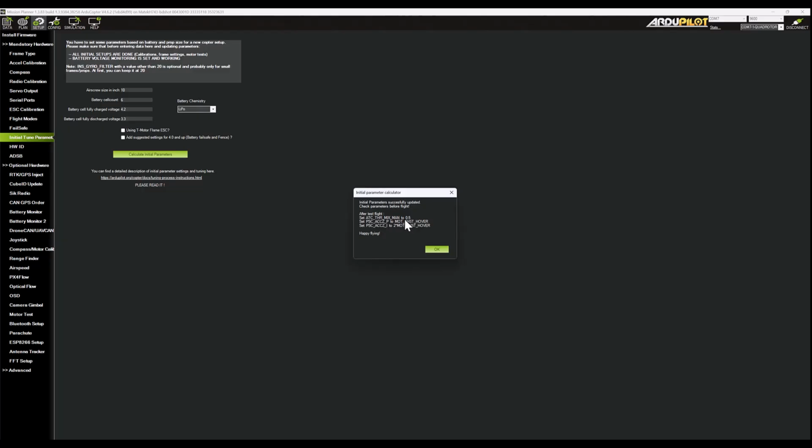By default, it should be balanced 0.5, but as for now, for the first flight, it's set to 0.1. So my recommendation, even if you're not going to learn anything during the first flight, set this parameter to 0.5. And a couple more parameters help your drone be more stable than just hold altitude.